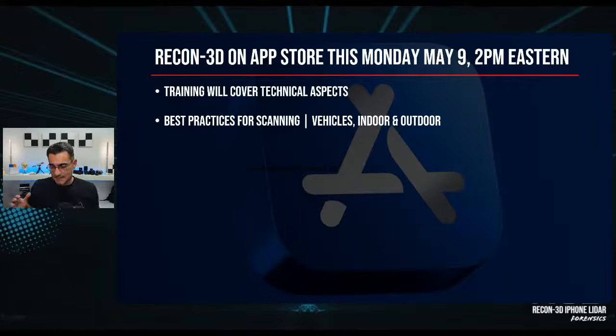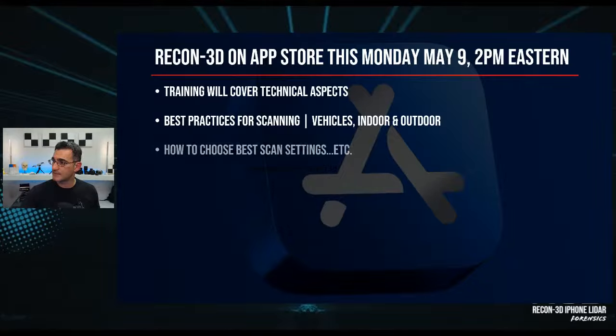And like I said, there are a number of different scenarios that you might find yourself in. I can tell you right now that if you're in a forested area and you're scanning a car, they are different. Okay, you have to prepare and you have to practice as well. That's an important part. So learn the best practices, then learn the different types of environments that you might be in, and then choose the optimal scan settings as well. You can't put everything at 1 millimeter and then think that you're going to get good scans if you're going to scan for 10 minutes. It's not going to work.